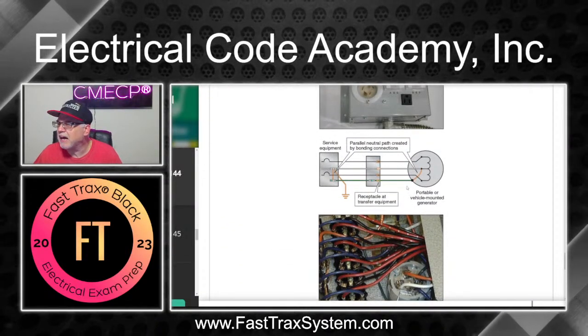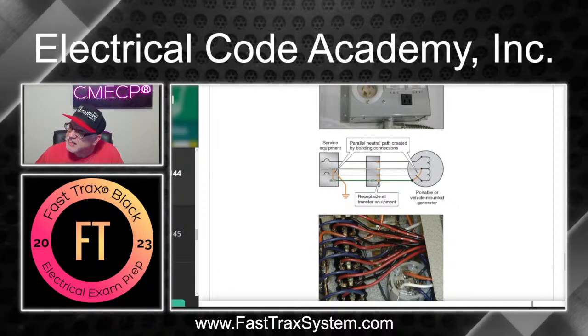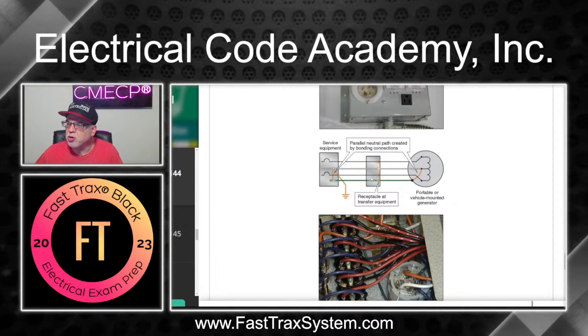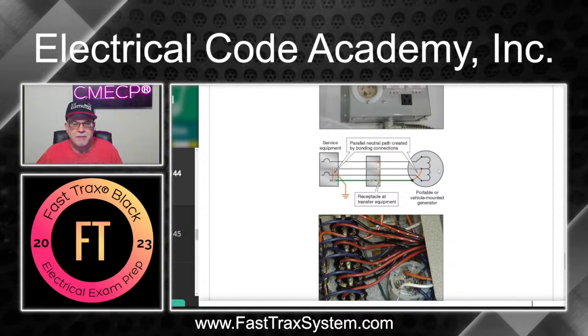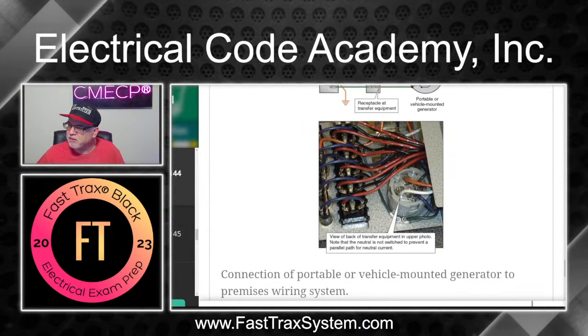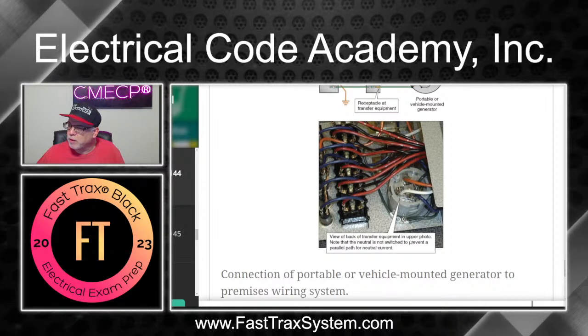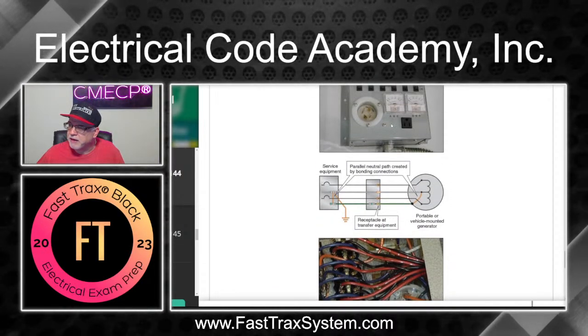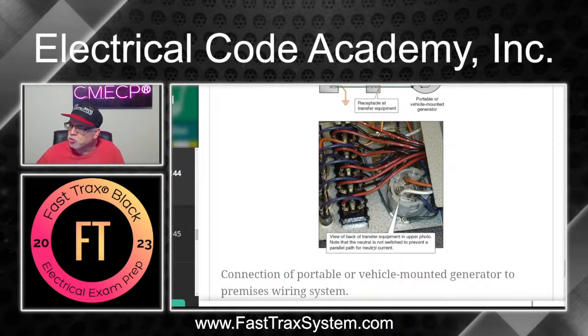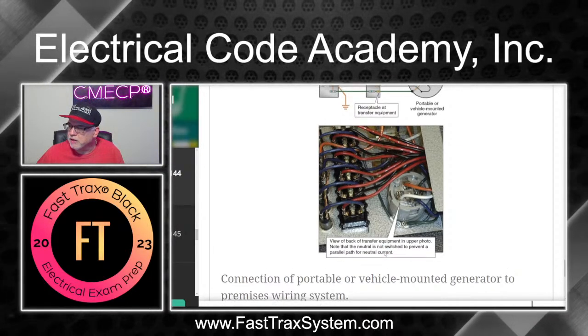All right, so here's what you've got. Because this is connected together right here, right, you have to switch the neutral in this transfer equipment, right? Well, this is a problem because they don't switch the neutral. And then this piece of equipment, if you look inside of it, you see right here, the transfer equipment, and this is the inside of one of these back here, by the way. This is opened up, turned open. You'll notice that the neutral is not switched to prevent a parallel path for neutral current.